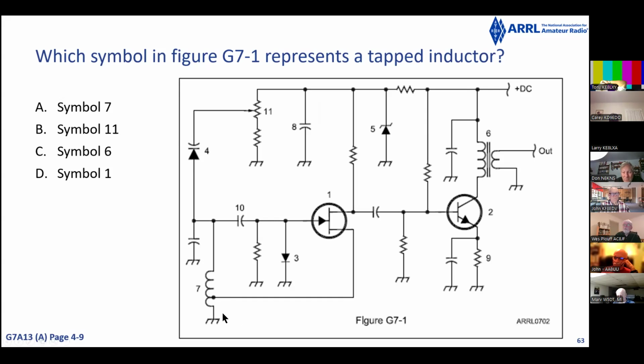Yeah, right. So you have one current that flows from the top to the bottom of number 7 there, and you have another current that flows from the tap where the wire comes in near the bottom to the bottom through fewer turns. And the idea is that makes that tap coil look like a transformer. So instead of 2 windings, you have 1.